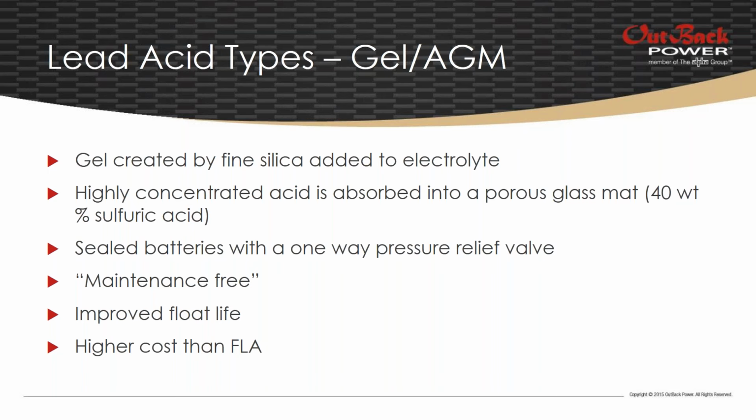So, kind of going along with that, these batteries are what we call maintenance free. We don't have to add water. They have an improved float life. So several of these, I should correct myself, certain gels and AGMs are made for backup applications. Those batteries have improved float lives, and a lot of them are greater than a decade. They have pretty long float lives. However, you do pay for these advantages. They are a little bit higher cost than flooded batteries.